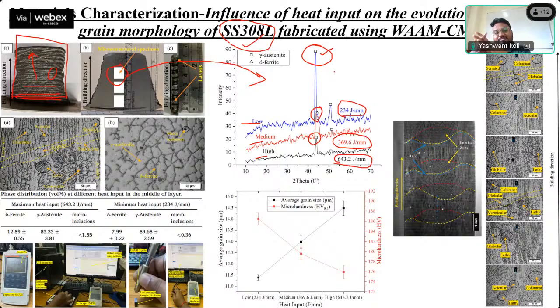You can justify this when we are melting the austenitic stainless steel, looking at the iron carbon diagram that everyone knows about. At low carbon percentage, the L here means low carbon, that is less than 0.03% carbon is used in this stainless steel.